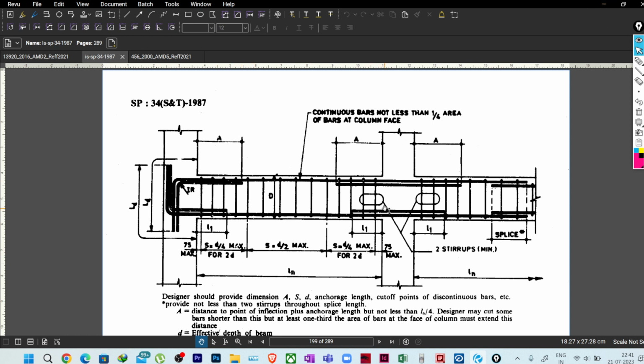Correct. There is one ambiguity that we will be facing about this extra bottom if required. I don't think in ductile cases we will get this kind of detailing, like one bar like this, and again another center bar, and again another curtailment bar. No, if it is required, it will be provided throughout, and extra end bars will be provided. So there is not an issue this much.